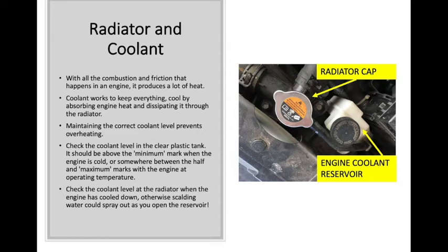Check the coolant level in the clear plastic tank. It should be above the minimum mark when the engine is cold, or somewhere between the half and maximum marks with the engine at operating temperature. Check the coolant level at the radiator when the engine has cooled down, otherwise scalding water could spray out as you open the reservoir.